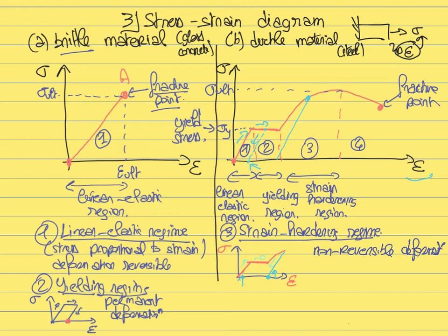So it means that now the material has a permanent residual deformation. And once you reload the material from this point, this is what it's going to look like. Initially when you reload, the material is going to behave exactly like it was a linear elastic deformation, where the stress is increasing linearly with the strain. If I draw it here, after you reload the material, this is how the stress will behave. And after you continue loading, then everything is going to continue from this point.